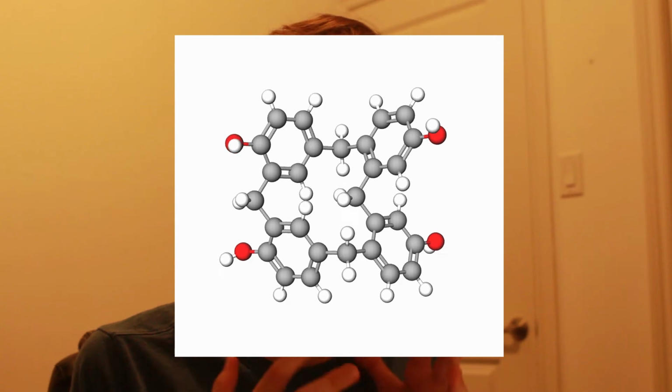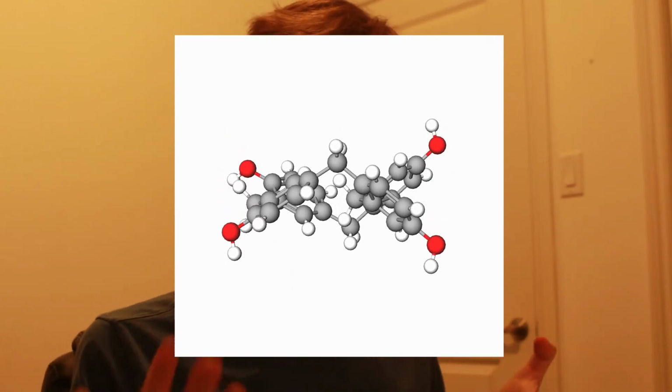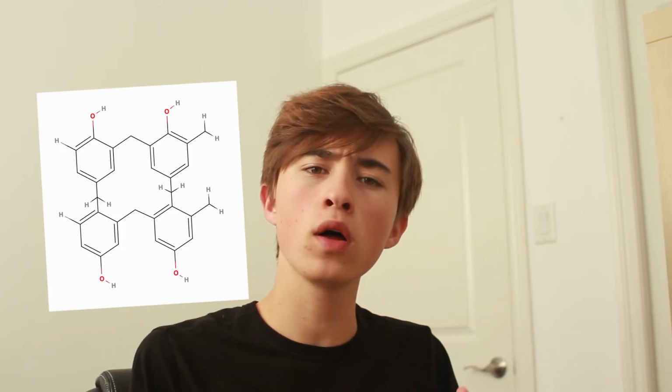So why is Bakelite so hard? Bakelite is known to be thermosetting. This means that after it's been molded, it turns into a solid, insoluble, unmeltable material. One thing is that the cross-links that make up Bakelite turn it into one unique molecule. With polymers like Bakelite, it's sometimes hard to predict what might happen to them once they're formed. Although you could have one super molecule, it's more likely you're going to have multiple very large polymers that interact with each other.